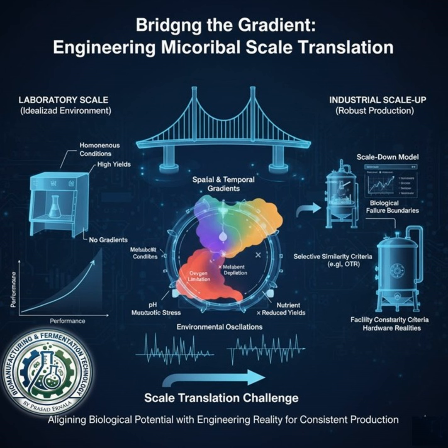Sure, think about antibiotic production with Streptomyces clavuligerus. This bug is extremely sensitive to pockets of high glucose. Right, if you feed it too fast in one spot. At large scale, if your mixing is poor, the glucose feed creates these intense local pulses, and that pushes the organism into acid-producing pathways, and your yields can drop by 15, even 25%.